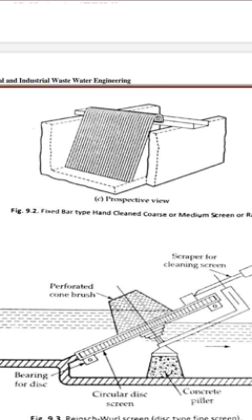So the screen chambers should be wide in the opening of the channel, so that you can smooth the entrance and exit. At the entry point it should be straight enough to keep the minimum velocity of the flow for self cleaning. That's why, for self cleaning purposes, the velocity has to be kept. The exit point should also keep the maximum velocity for the dislodging of accumulated solids.